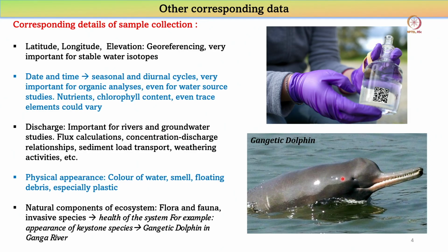Okay, so therefore, based on the parameters that you're going to analyze, you need to know beforehand whether you should take a diurnal cycle, and at what particular time it is best that you take a sample. Okay, so that is extremely important to note down, right?